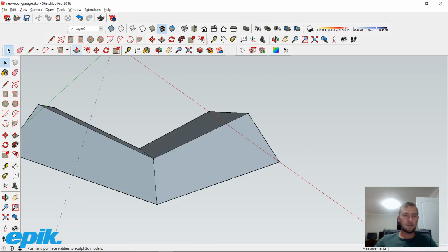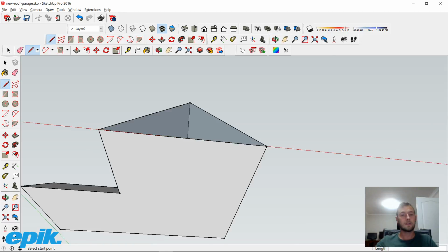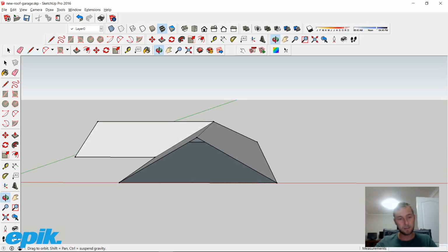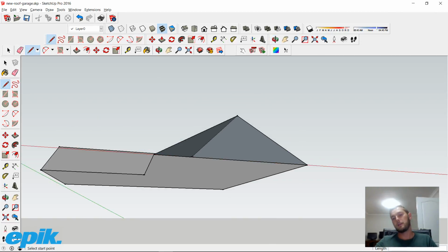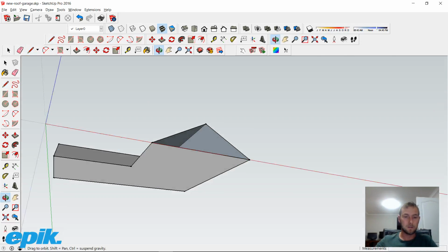To create the ceiling, we're going to box this in on the actual edges. There we go. Not the best looking ceiling just yet. If you guys know what a roof looks like, the ceiling doesn't butt against the actual edges of the roof. The roof usually has an overhang. In most cases it's about 600 millimeters.